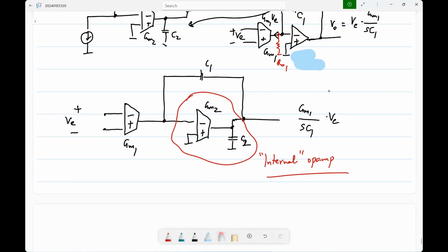This is okay. Now, of course, you have to put in all the details and then analyze this, because now you have a more complicated circuit. And one thing I have not shown here is there will also be a parasitic capacitance here. And so on, right? So these things have to be changed. Maybe it is better I call this C and I could call this C1. Anyway, whatever it is, there will be some parasitic capacitance here. You have to analyze it. But that part you already know, the circuit analysis, and we will again go through it. But it's important to understand how we got the topology.